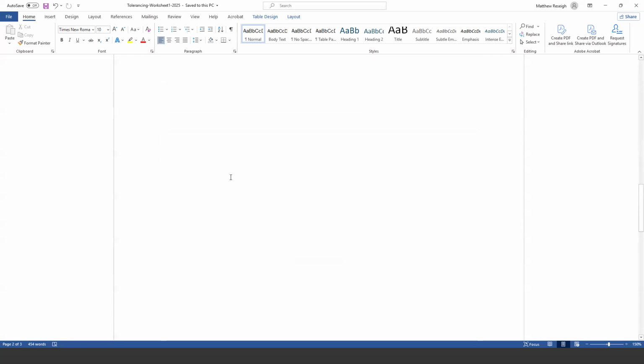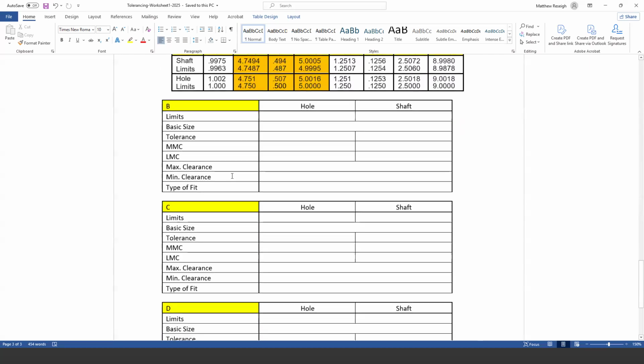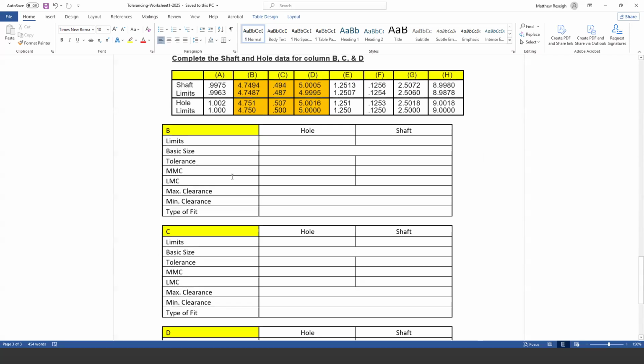All right, so that's how we would do it. What's that? Yeah, it's really not a problem. Some parts are designed to have interference like that. If it's not designed, it is a problem. Like a metal shaft through a nylon, with the heat up. Exactly what I was just going to say.